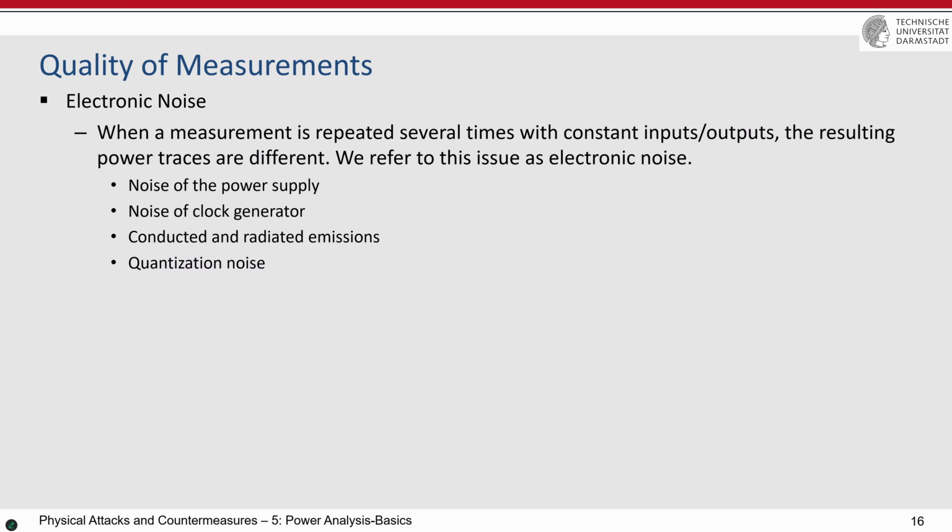And the quantization noise is something else. We explained that even if the signals are super nice, if they go a bit higher or lower, they drop into the next level of the quantization or the higher level. Because, as I explained, if you have an 8-bit ADC, then there are 256 levels that you can quantify. Then it may change from one level to another, even if there is not much electrical noise in the analog signal.